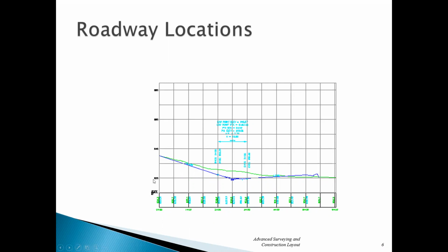The numbers over here, 820, it looks like 840, 860, it's hard to read those, but those are elevation values. Okay, so that's no different than we saw on the sewers, but what we do see, a green line here is our existing ground line along that alignment, and the blue lines here, these are representing the actual center line elevation values of that alignment or that profile.